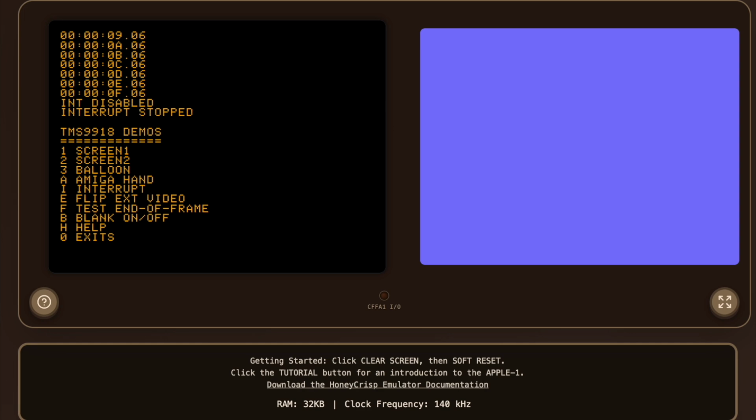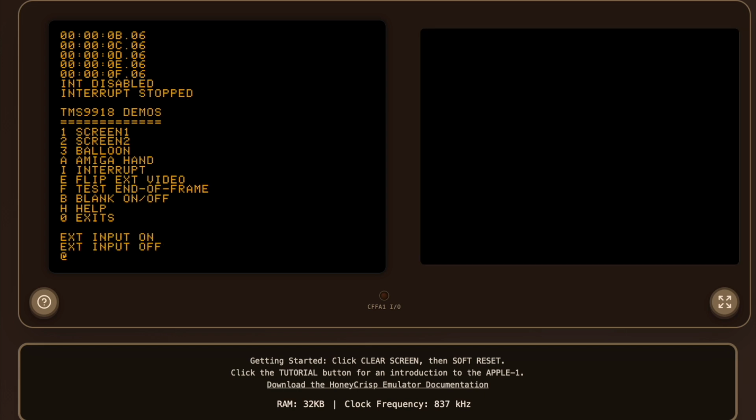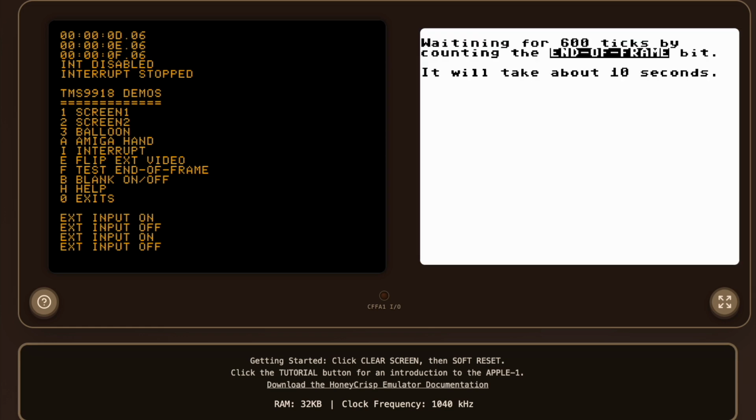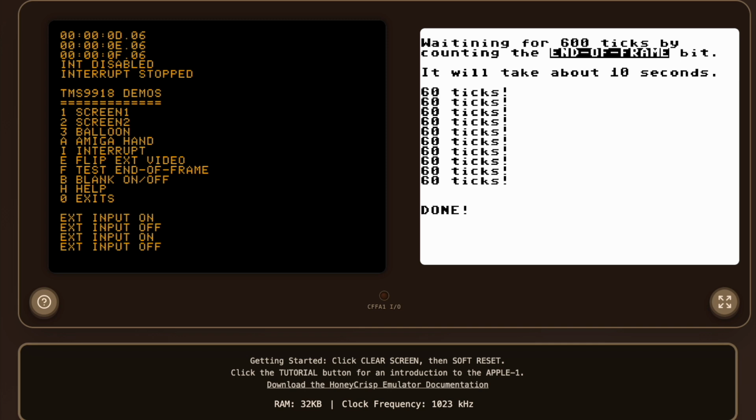First, you have Graphics 1, which gives you a 256 by 192 pixel grid, but the color is only assignable in groups of 8 characters at a time. Graphics 2 keeps the same resolution but resolves color per 8 pixel scanline instead, which means that every character cell on the screen can have its own unique bitmap and color data. And that's actually what makes true bitmapped images, one of which will be showcased later on in this video, possible